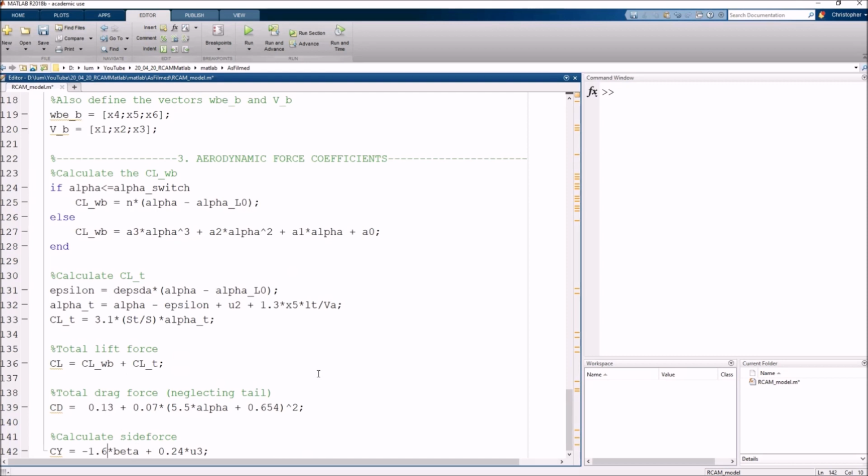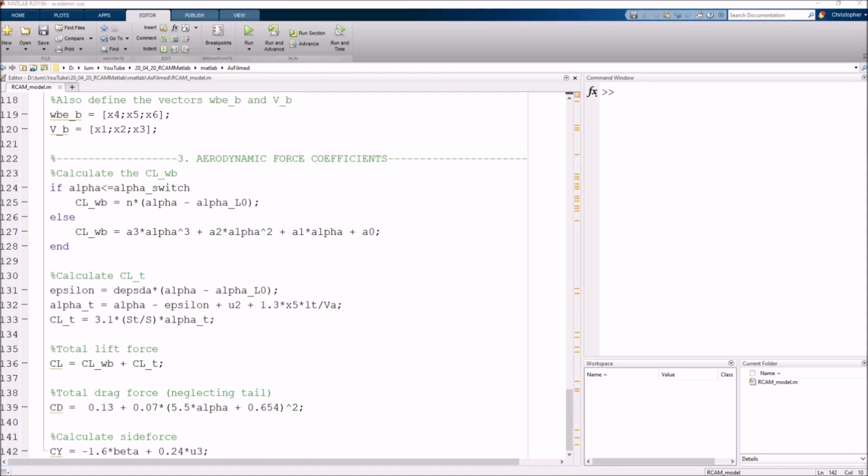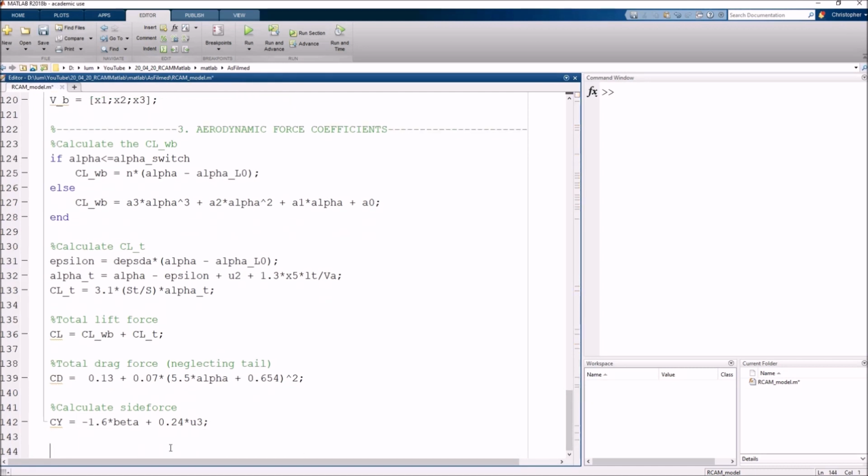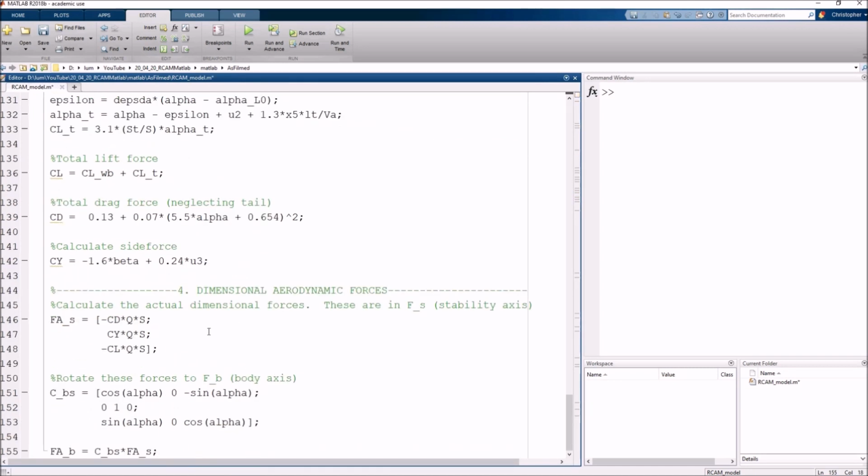So, there we go. We calculate all those dimensionless coefficients, and then the next thing we can do is move on to step 4, and we are going to go ahead and dimensionalize those. Again, I'll copy from my prepared script off screen, and here we go. We will stack up all of the coefficients, and we will put the appropriate sign and put them in either the force in the x direction, the y direction, or the z direction here. And we will then scale them all up.